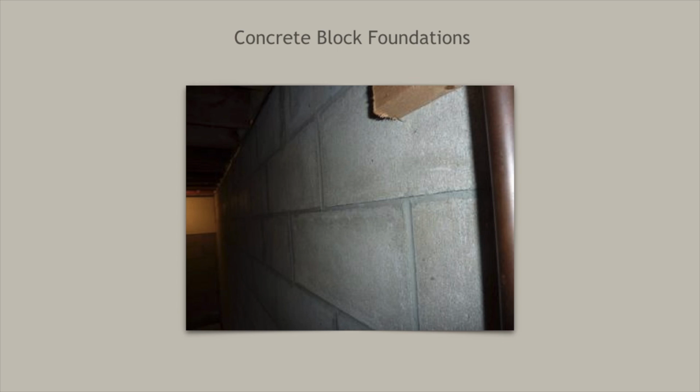in width. These types of foundations had to be completely covered with cement coating on the exterior and coated with a heavy, brushable tar to prevent the ground and surface water from entering the block foundation. The biggest problem with this type of foundation is that if a leak occurred on the exterior, it could appear in a completely different location on the interior.